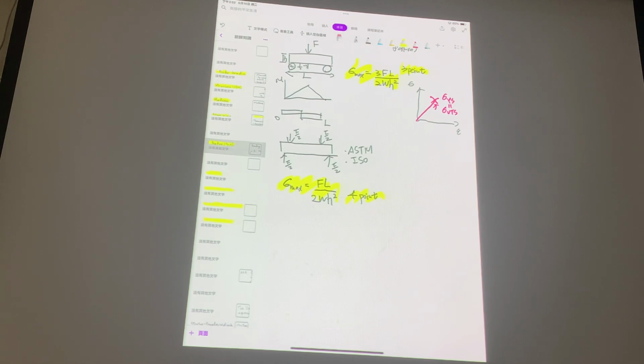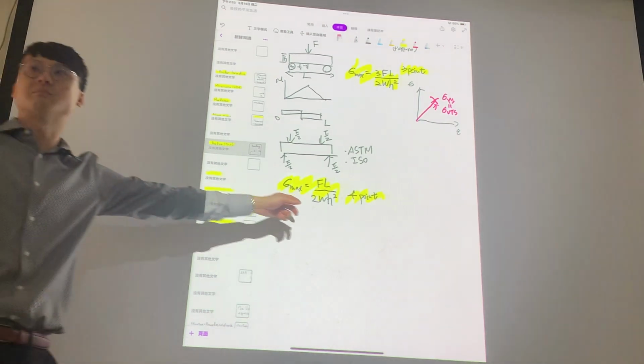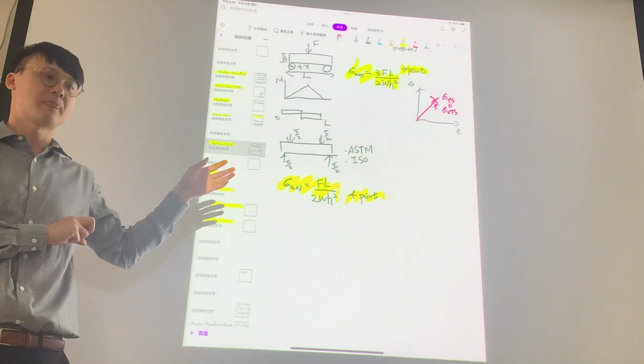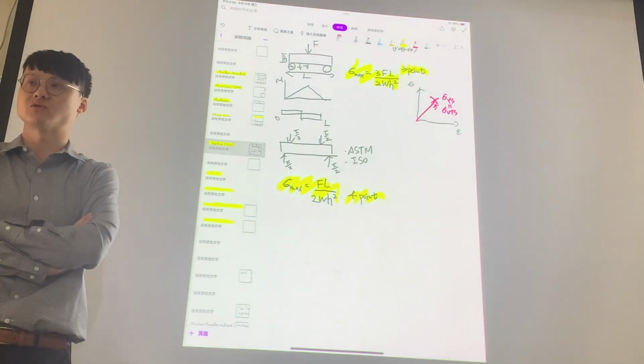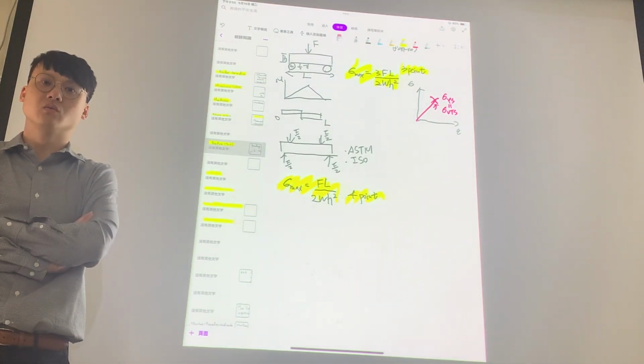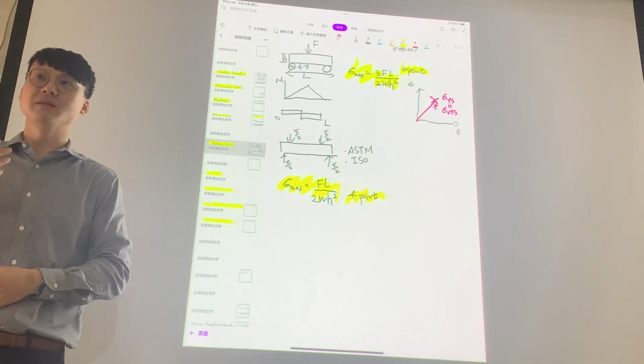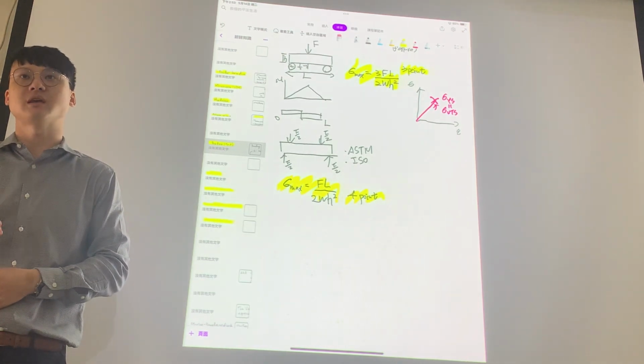The question then comes to the bending modulus. When you look at a technical data sheet, sometimes they will provide it. So over here, you get the modulus as well. The modulus I didn't really give you, but you can use these values to calculate it. 就是那个杨氏模数，你可以借由这个值去算出来，我只是没有给你。如果你去复习你的材料力学，都可以算出来。So the bending modulus that you get is not the same as the tensile modulus.